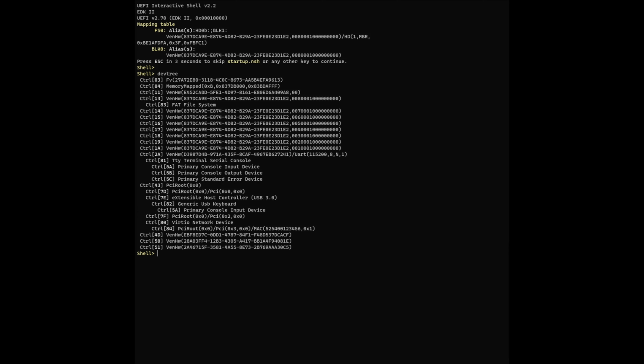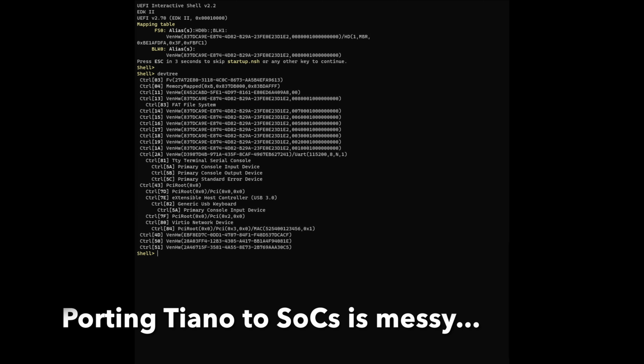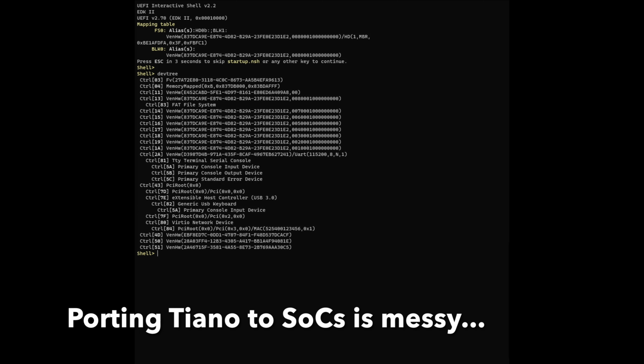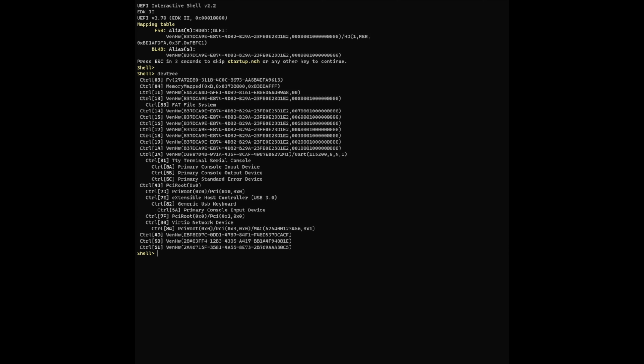For example, the Serial Console is provided by SerialDxe, which uses the SerialPortLib to abstract hardware and supports only a single device. Writing drivers for typical, non-discoverable devices in modern system-on-a-chip designs is, well, complicated. You need to figure out how to describe the devices and their dependencies.